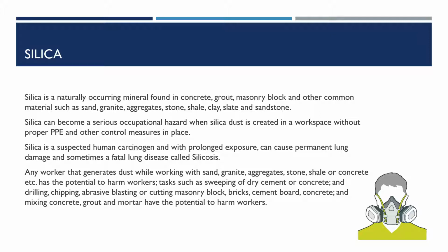Any worker that generates dust while working with sand, granite, aggregates, stone, shale, or concrete has the potential to harm workers. Tasks such as sweeping of dry cement or concrete, and drilling, chipping, abrasive blasting, or cutting masonry block, bricks, cement board, concrete, and mixing concrete, grout, and mortar have the potential to harm workers.